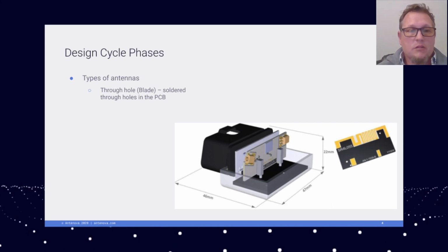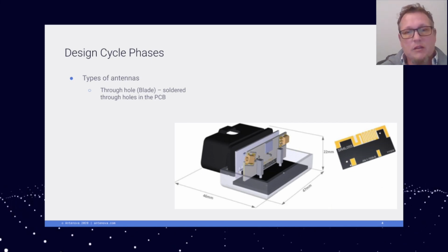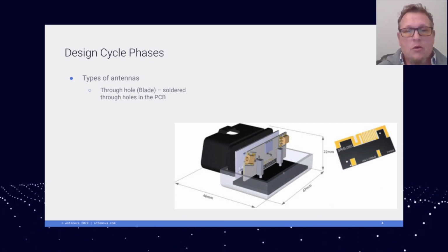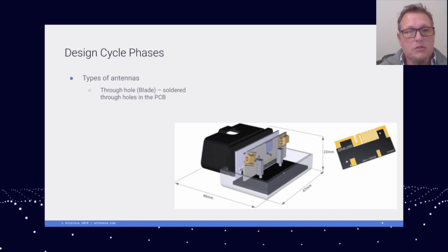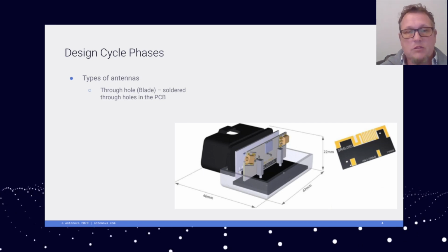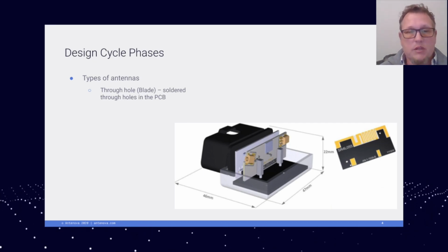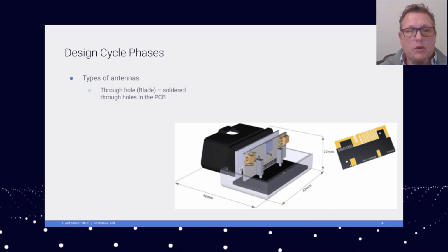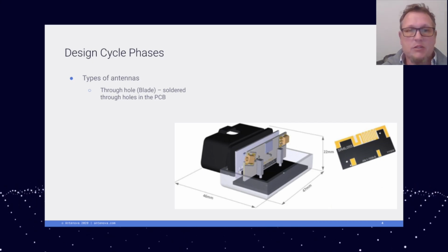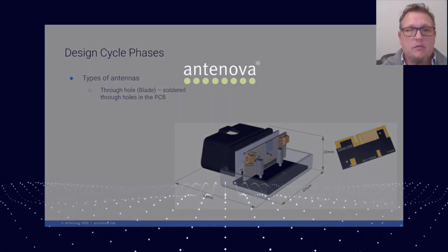Those can be added to your design by using pogo pins, or if you need something a little more robust, you can solder header pins to through-hole vias on your board and then to the antenna, or use a C-clip soldered to the main board and touching on landing pads on the antenna itself.